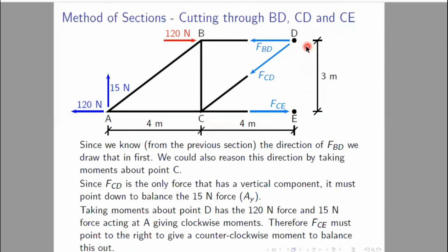Now, you need not mention other points on the right hand side, but for the member force at the place where we are cutting, while mentioning the member force, it is very important to identify from which direction the member force is coming. So you have to mention the points D and E only in this particular case. So these are the unknown member forces.